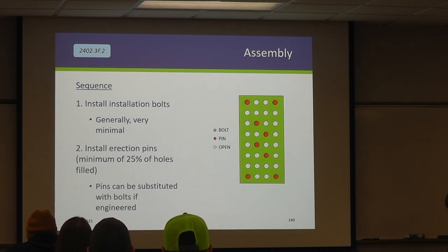This is a spot where the contractor may tweak things a little bit up and down with their crane to try to bring everything into alignment. If they do a good job, especially if they have a good crane operator, those drift pins shouldn't need a huge maul out there hammering away. You really should be able to slide them through with a simple handheld maul. I've seen jobs where they come out there and they're swinging away like they're chopping wood to try to get that drift pin in. Something's not right. Even though it's the same size, they really should slide in.